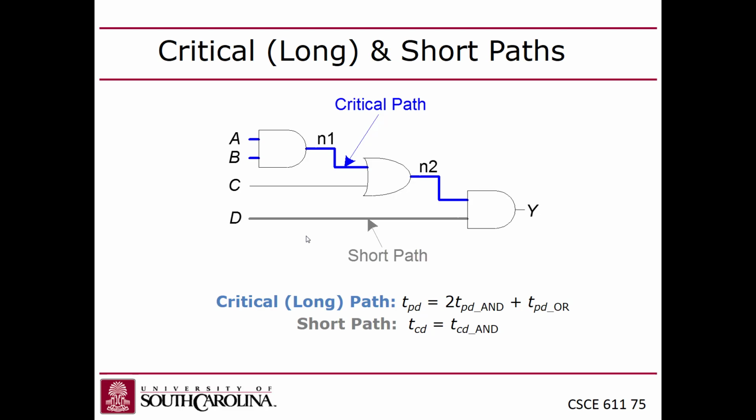And the reason why is because the disadvantage of sum of products is that as you make a sum of product circuit bigger, the OR gate at the end gets bigger, right? The OR gate has to have 1 input for every minterm, or for every implicate. So that's going to get to be a giant OR gate at some point, right? Let's say I might have a whole bunch of inputs into that OR gate. And in reality, real standard cell libraries, gate libraries, generally don't have many more than 3 or 4 input gates at most, because it's not really practical to make a gate with a lot of inputs.